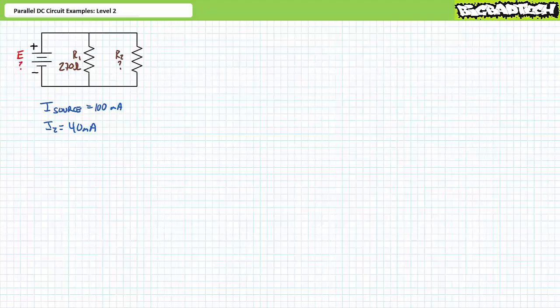My sincere advice for every single one of these scenarios is to lay out everything you do know about parallel circuits and apply these fundamental properties to the circuit in question. Ideally, you should be able to use the provided clues to make deductions about or to solve for other properties. You will no doubt recall that voltage across elements in parallel is the same. This is the most fundamental parallel circuit property. Additionally, Kirchhoff's current law states that for any node, the summation of incoming currents equals the summation of outgoing currents. In short, what goes in must come out. Finally, power in always equals power out. We can use this fact to solve for other properties or to check our work.